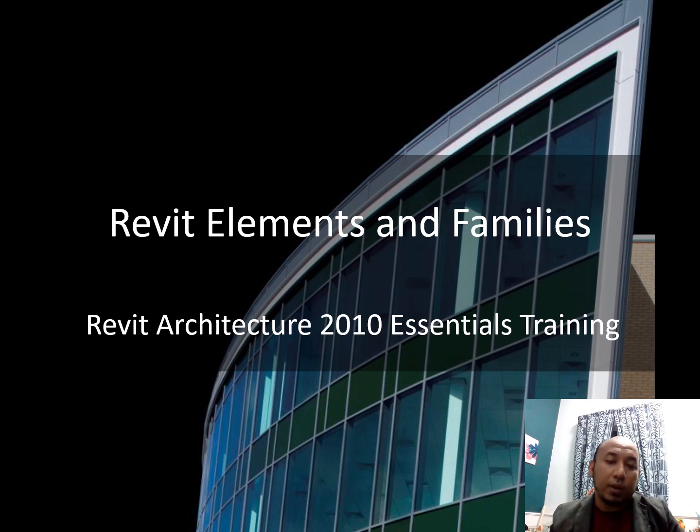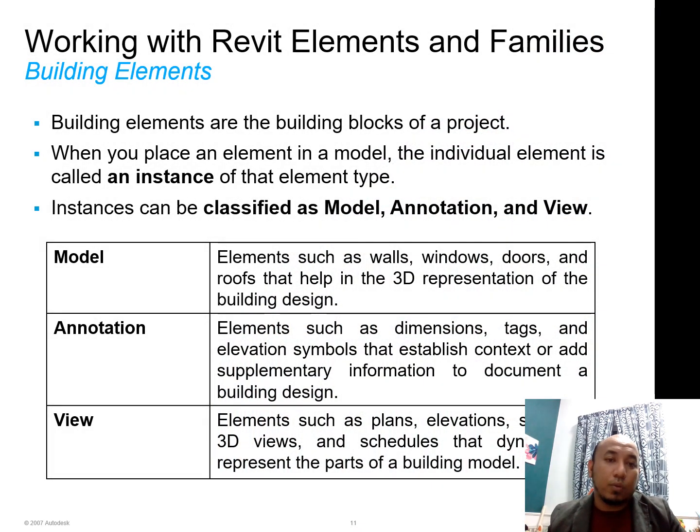We go through the next subtopic, which is Revit elements and families. Building elements are the building blocks of the projects. When you place an element in a model, the individual element is called an instance, an element type. Instances can be classified as model, annotation, and view. The model